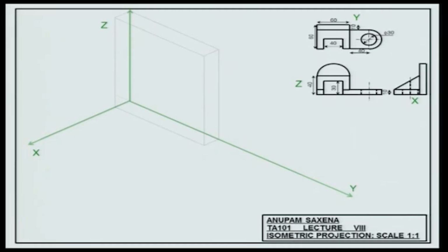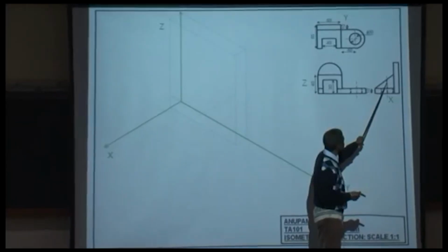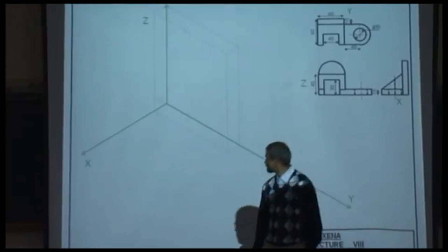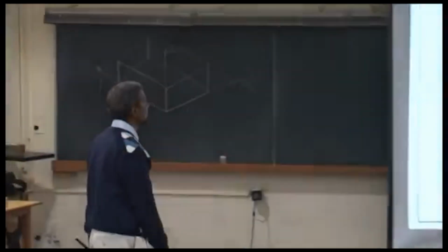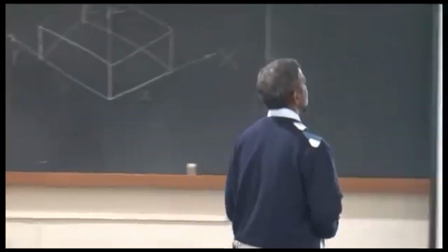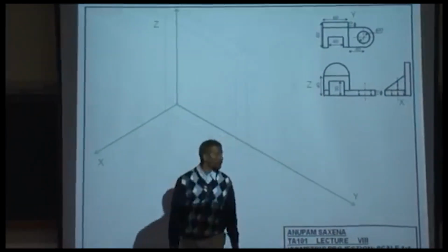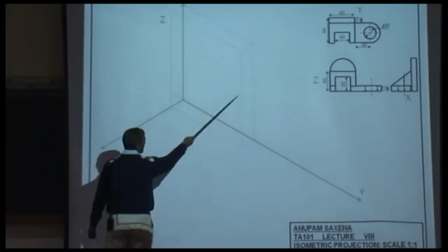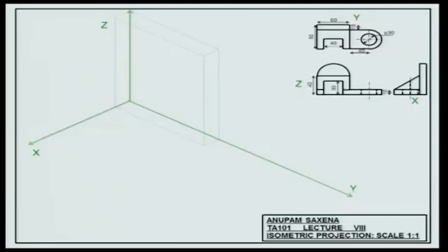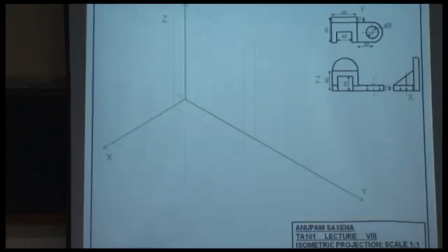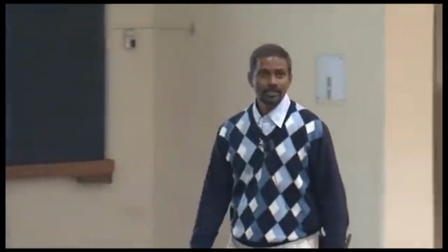Okay. So I'm drawing a block that would encompass this feature here. What is this length? 50. Right? So 60 minus 10. Okay. What is this height? 40. The same dimension, got one face. If I got one face, all I need to do is draw lines parallel to the y and get this block. How about the third one?